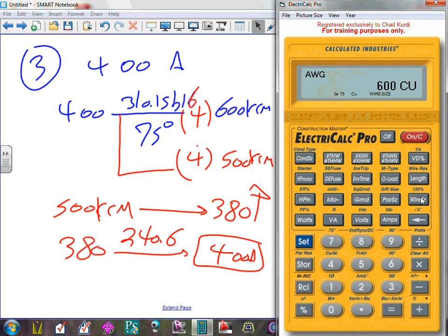A feeder or service neutral load shall be the maximum unbalance of the load determined. The maximum unbalanced load shall be the maximum net calculated load, blah, blah. For 3-phase, 2-phase, okay, 5-wire, permitted reduction. Feeder service supplying a household electric range and prohibited reduction. We'll go through the calculation, guys, on feeders. Okay, so that's for feeder calculation.